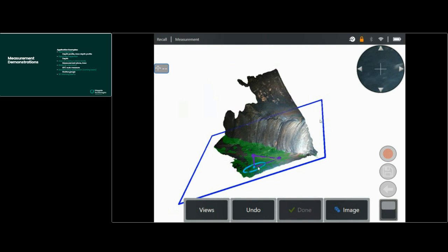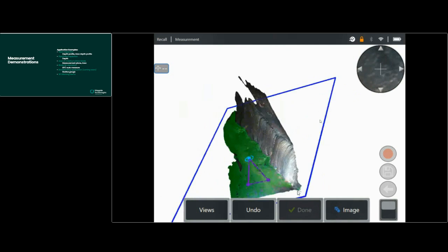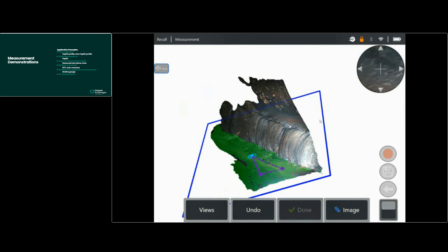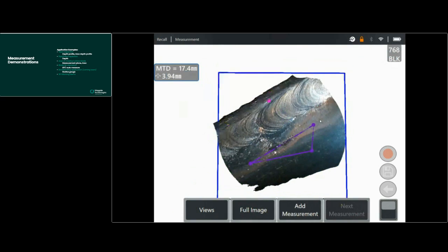And as Clark was saying earlier, make good use of the 3D surface mask. Make sure you've got a good agreement between all of the points in your reference plane by determining a good amount of green surface in there. And the fourth point, from a depth point of view, is then projecting a distance, a length in this case, that projects above the point cloud.